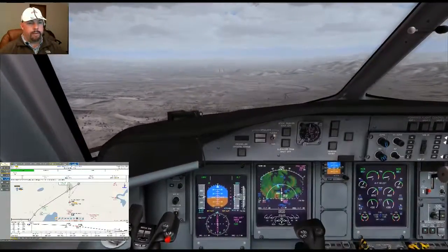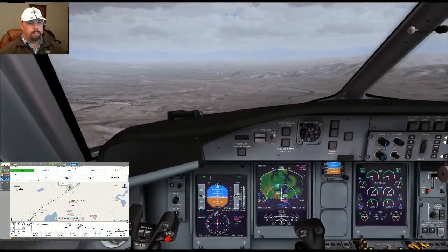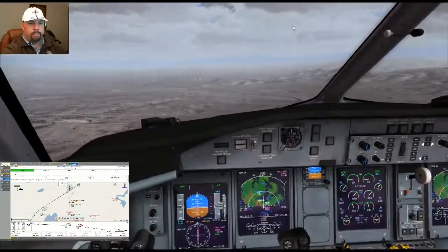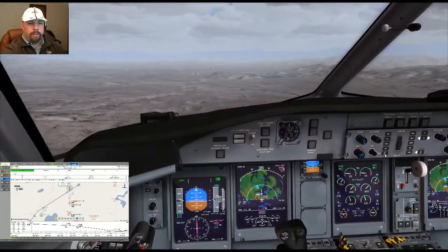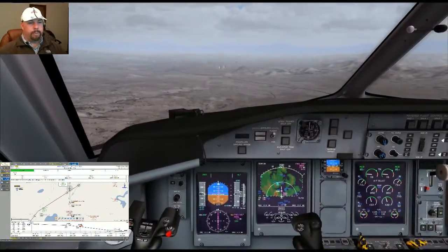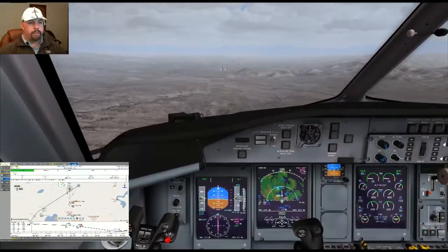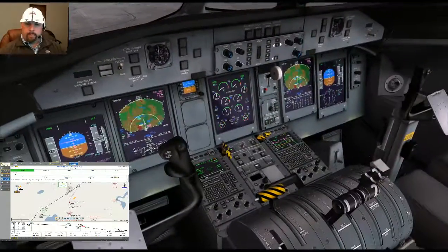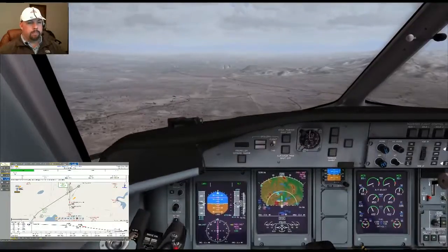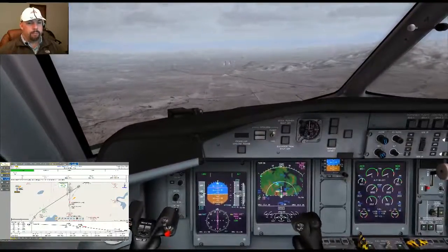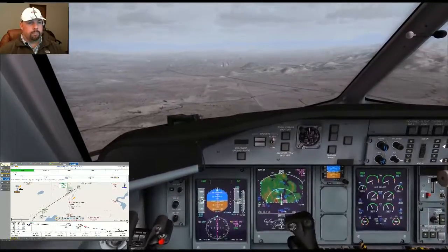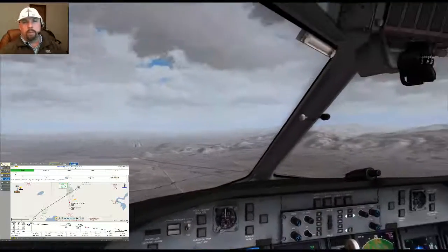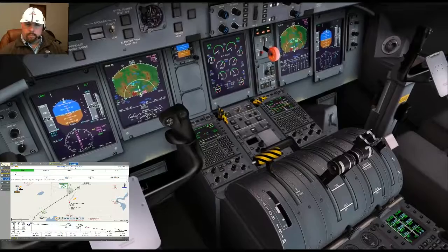The aircraft will level off at 6,800 feet, and as it does, I'm going to go ahead and disconnect the auto-flight system. I will continue descent down to 4,700 feet. Again, we're going to shoot for about 750 feet per minute, according to the chart here. Go ahead and start to configure for landing as well. So, flaps 5. We have flaps 15 landing. Gear's coming down. Flaps 15.